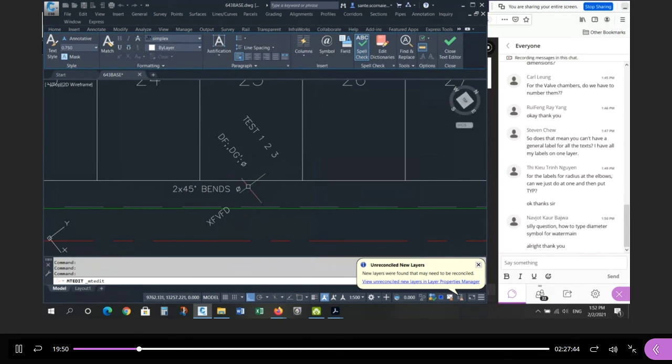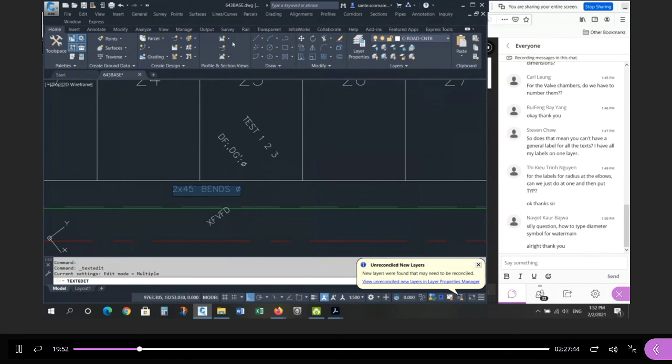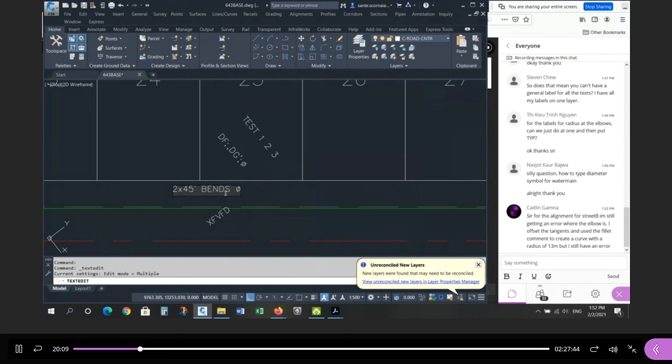But you don't get this ribbon with D text. If I double click here, you're not going to get that ribbon. So here you have to really know what the codes are. Like I demonstrated last time, you can actually look these up. There are a lot of blogs or internet websites where people have documented all this stuff.